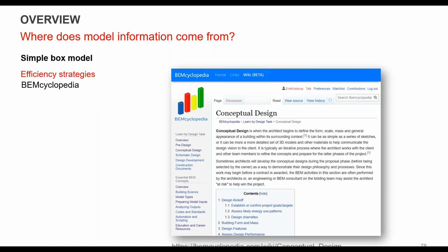The intent was that instead of a municipality, or even a state, saying that they wanted to adopt a minimum LEED target, to say you need to hit LEED silver or something, because that's very specific, you have to pay the program fees and do all this stuff associated with LEED. There's cost. They could just adopt 189.1, which is nearly equivalent to achieving a certain LEED rating. So that's the intent, is that municipalities could adopt it and say, by doing that, we're basically saying everybody has to build to LEED silver or whatever it may be.